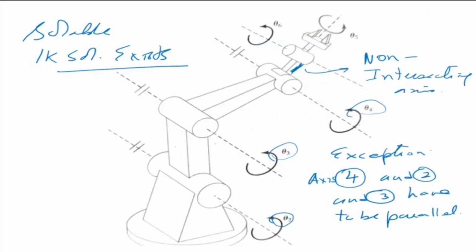Okay, so let's look at the previous example. So in this particular case, you see that the heaviest motor will probably come on the base. So the heaviest motor is going to come on the base, and it will be mounted on the base somewhere in there. So this is my motor, which is mounted with a bevel gear onto the first link. So one more motor could be mounted here. So this is for the first joint, which is a rotating joint about this axis. Okay, the second joint is here.